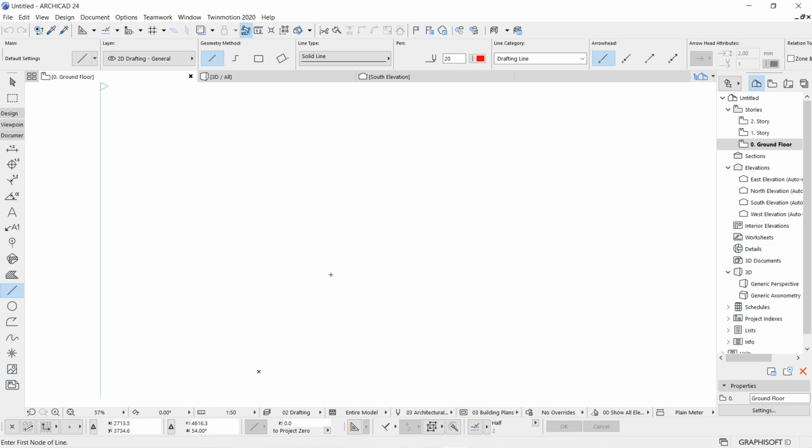And what I'm going to do, listen very carefully, is hit X from the keyboard. The character X I'm going to press only once, and you will see the X field is activated, where I'm going to type 0. I'm not going to use enter now. Be careful, I'm not going to use enter. Then I'm going to press Y, and again press 0, and only after that I'm going to use the enter key.